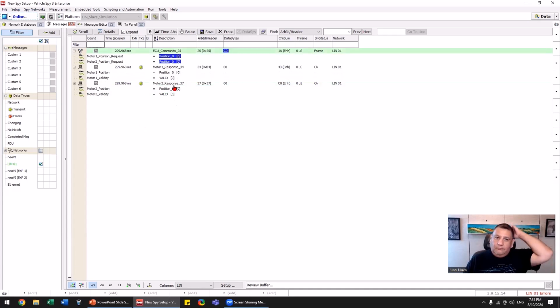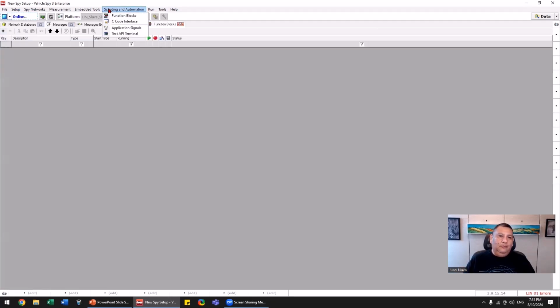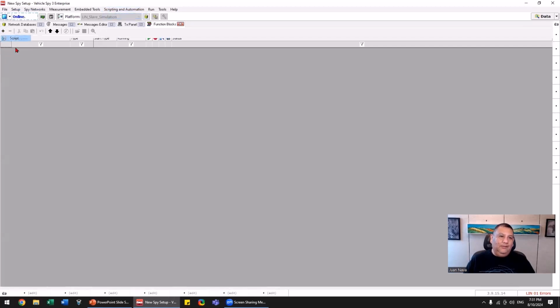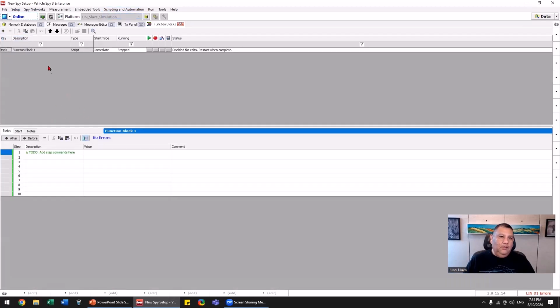Here, in order for me to actually respond to what the master is requesting, I'll need to create a script. And for the sake of this, I'm going to create a real simple script. I'm going to go Spy Networks. I'm going to go Spy Script and Automation Function Blocks. I'm going to click Script. And then I'm going to call this Motor 1 Response. Here I'm going to do an if statement.